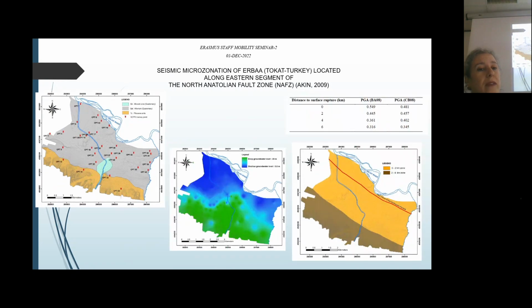And with the CPT applications, we have some limitations because of the gravel effect in that region. So we couldn't go further down until 30 meter depth. So we have especially used SPT boreholes, which have a 30 meter depth, which would be necessary for us. I also prepared the groundwater table.